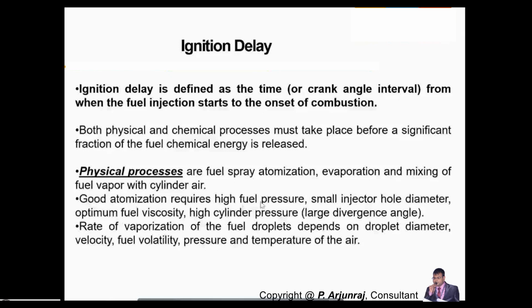And again, good atomization requires high pressure and a small injector. For good atomization, you need to have a high fuel injection pressure. That's why the injection pressure of diesel is going to be higher. It is coming nowadays up to 2500 bar in the case of Toyota engines.